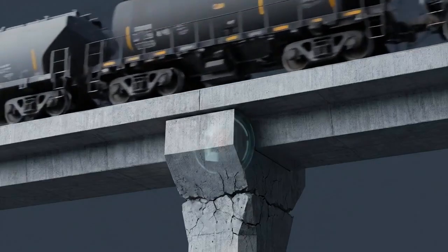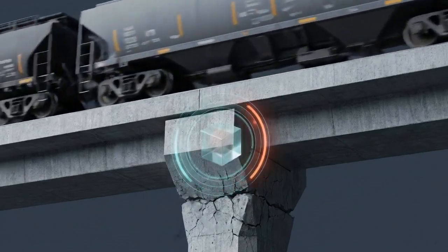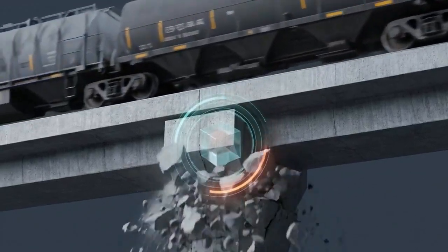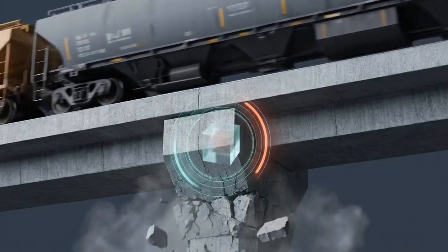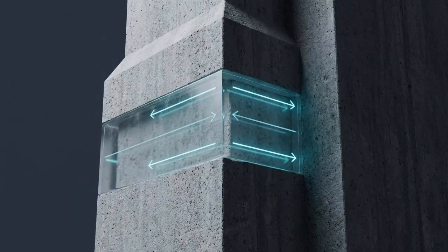When an engineer calculates the vertical shear stress pushing down through a bridge support, they are actually measuring a forced byproduct. That vertical force exists entirely because microscopic horizontal imbalances are fighting to keep the beam together. This diagram shows a standard rectangular beam overlaid with a glowing heat map of that shear stress. Looking at the distribution, the stress is absolutely not uniform across the material.